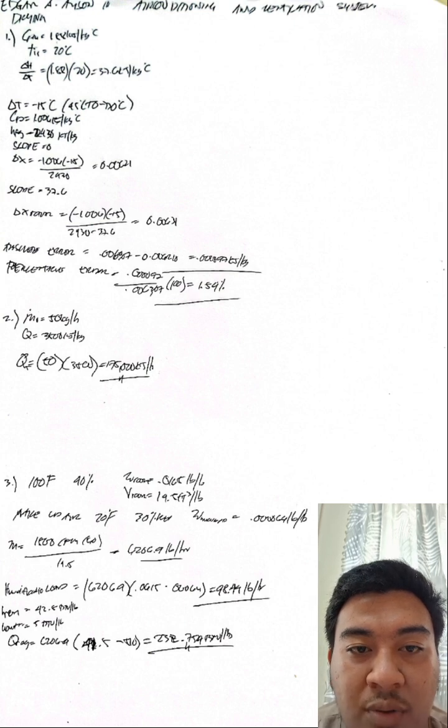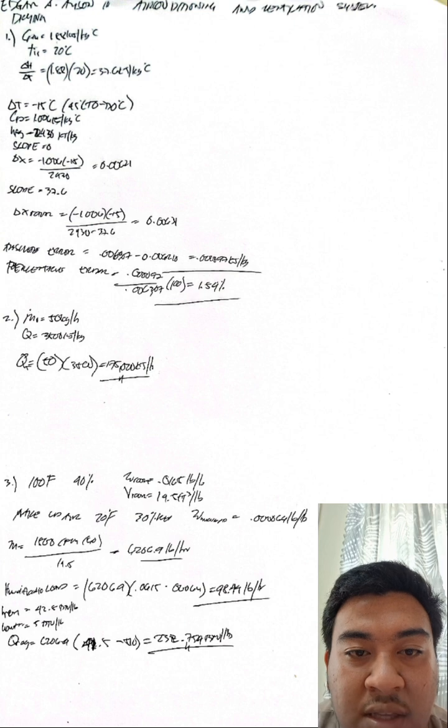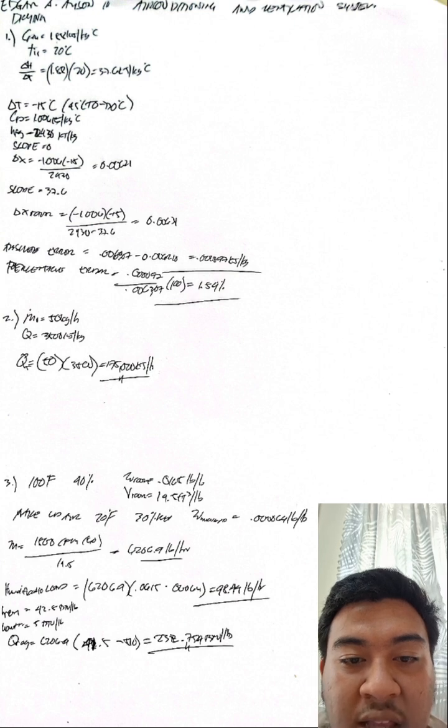We need to find the slope of the drying process line on a Mollier diagram and check the error if we assume an isenthalpic process. So to find the slope, we use the formula Cp delta T plus Cp times temperature over hfg. Plugging in the numbers, air specific heat is 1.006, delta T is 15, and specific heat is 1.88, material temperature is 20, and latent heat of vaporization is 2430 kilojoules per kilogram.